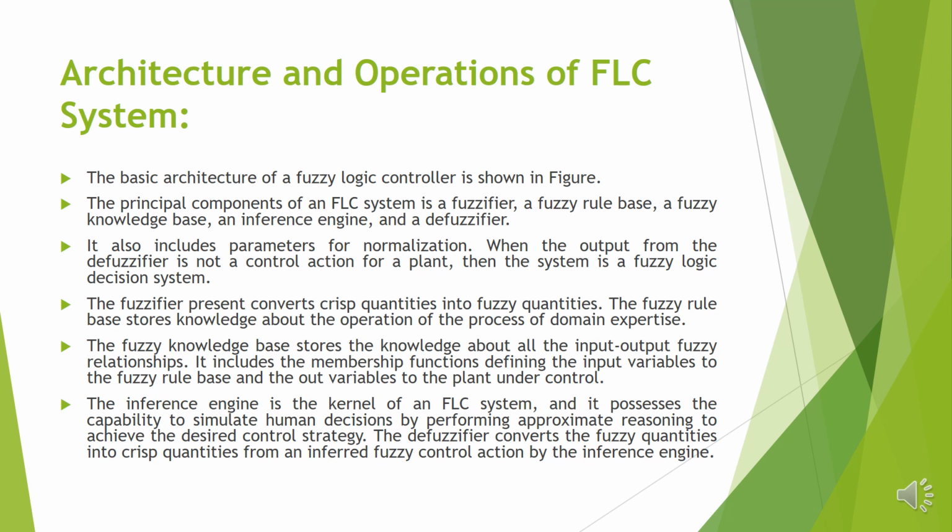The fuzzy rule base stores knowledge about the operation of the process and domain expertise. It also stores the knowledge about all the input-output fuzzy relationships. It includes the membership functions defining the input variables to the fuzzy rule base and the output variables to a plant under control.